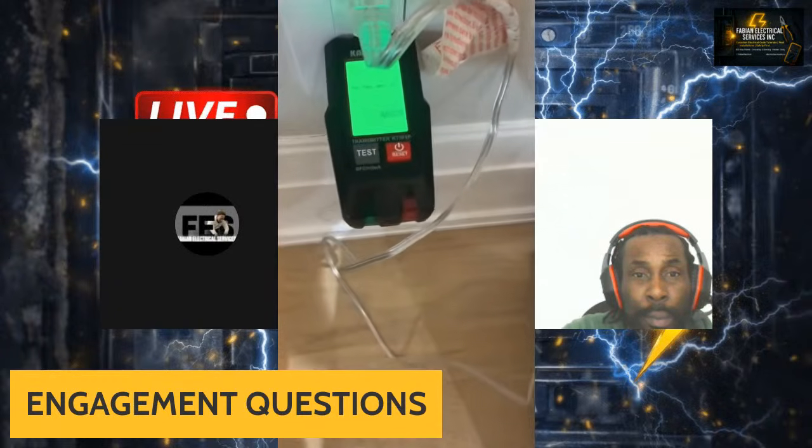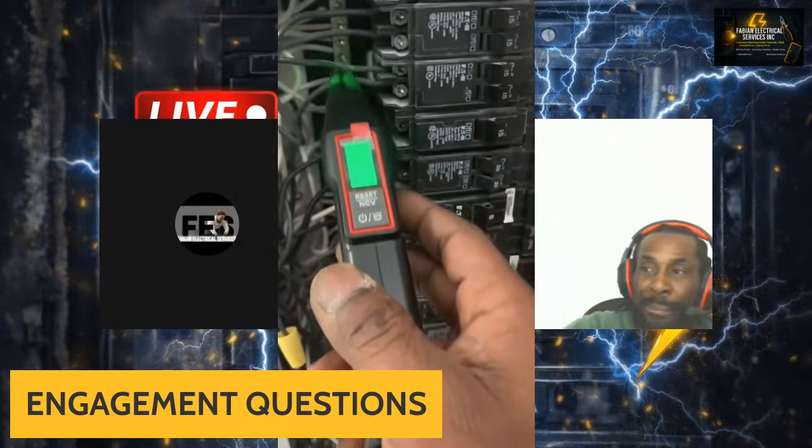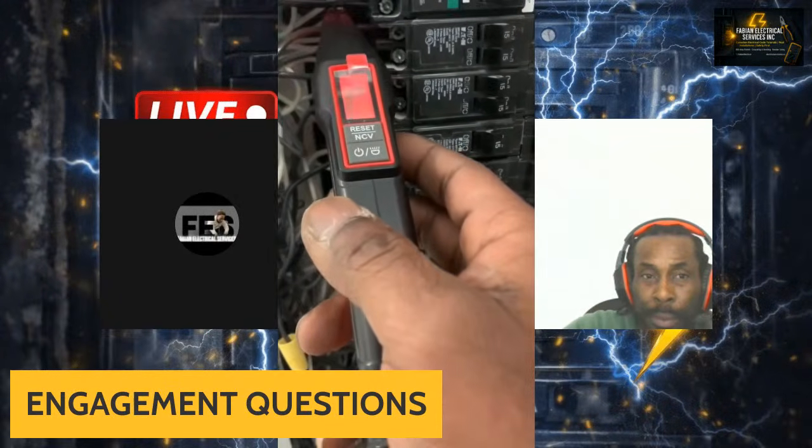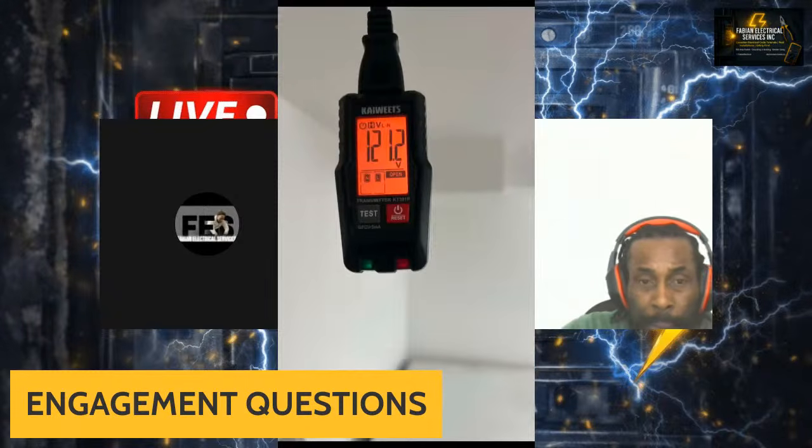Most electricians are using breakers wrong. A breaker protects the conductor, not the device. A 20 amp breaker can only carry 16 amps continuously. That's the 80% rule. Anything running over 3 hours, that's a continuous load. If you don't size this properly, you're setting yourself up for failure.